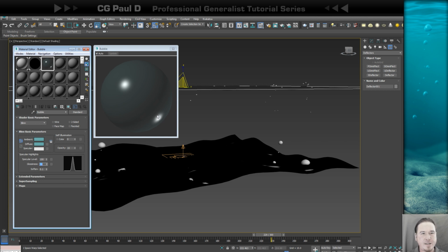And you'll see the little secondary highlight down here is also pretty circular. Oftentimes you kind of want to get a nice little rim light on it, and the blend function doesn't do too well with that. So I usually switch that one to Phong, and you can see the difference. It kind of adds a little arc to the highlight.